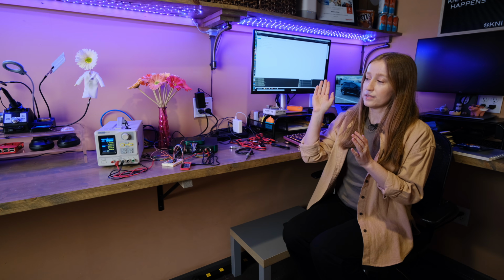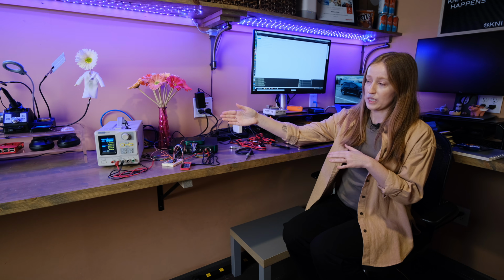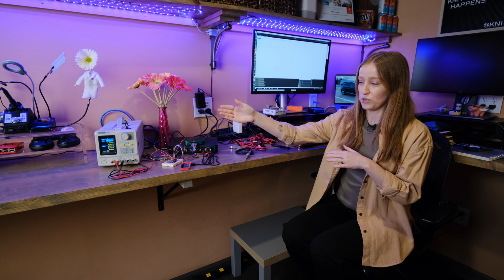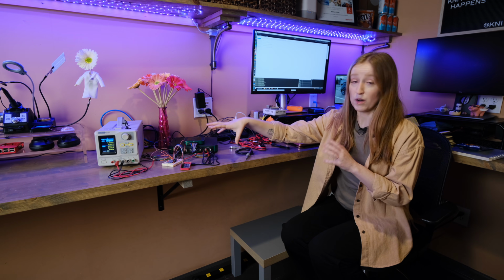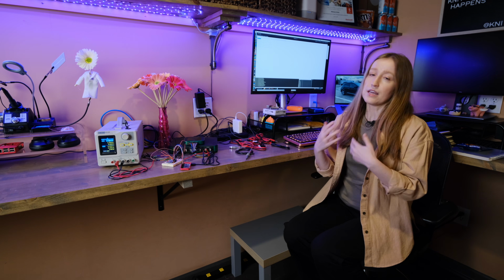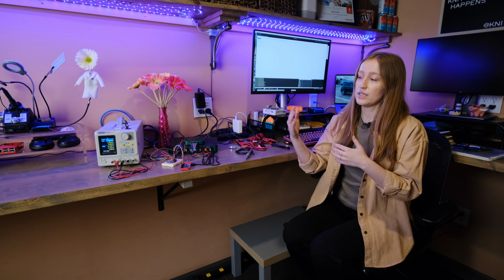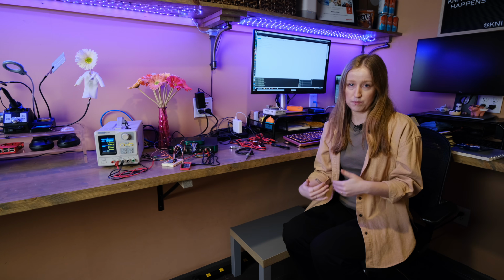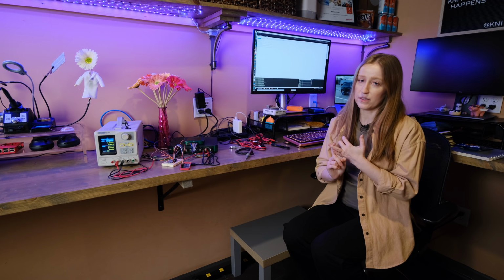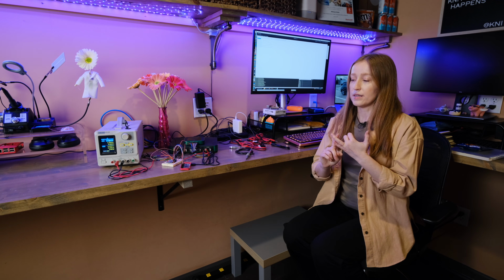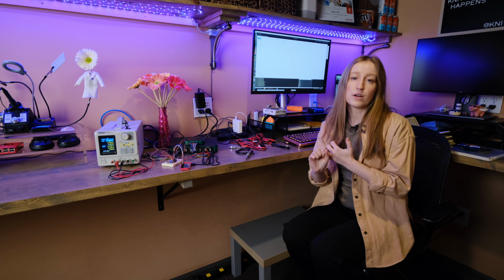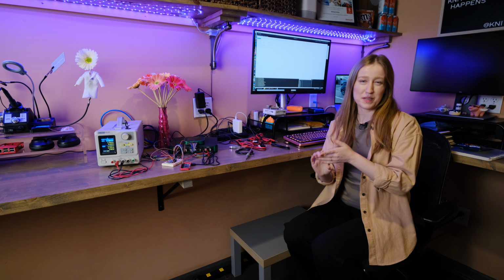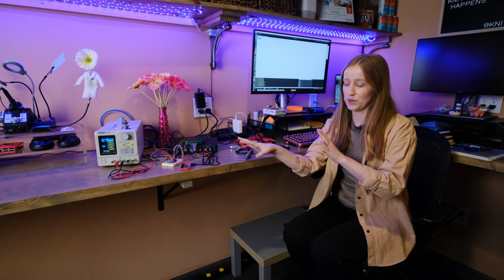So I have my SCPI command controlled power supply to turn my whole setup off and on remotely. The other aspect to that is not only can I control it via the SCPI commands, I can also read the current back. That's a big deal because that tells me A, is something wrong, and B, that'll give me a clue where things in my test setup are in the boot process. That'll become important later as I go through the whole setup.